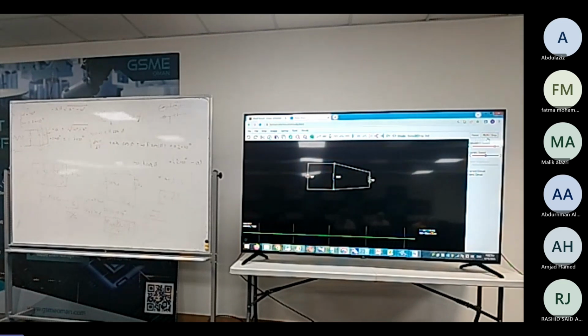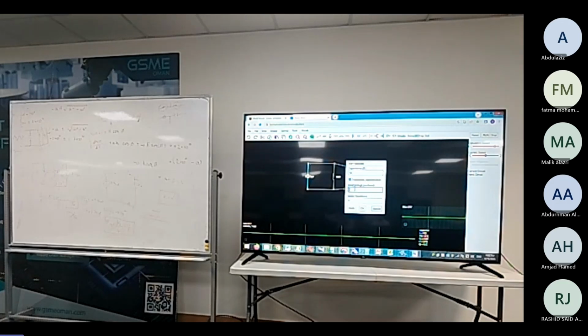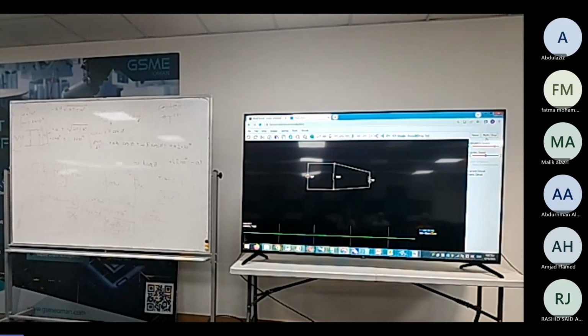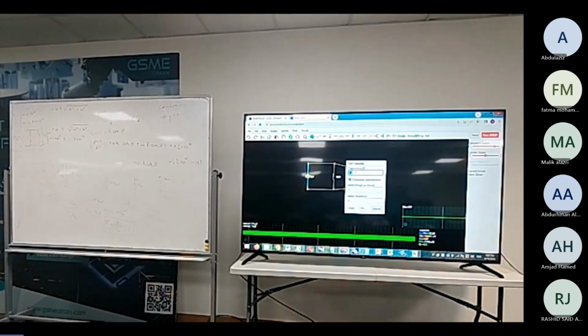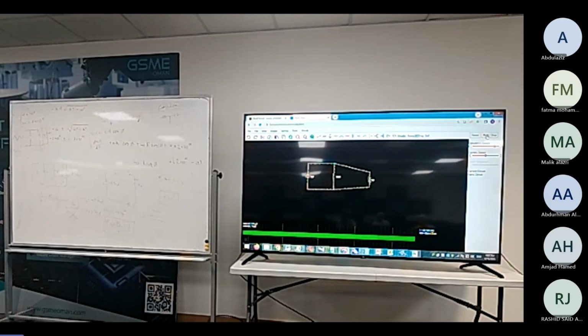One uses transient simulation, solving the differential equation. And the other way of solving is based on assuming that every signal is the result of different harmonics. So it tries to solve for all the harmonics and put them together to generate a signal. That's called harmonic balance. And in the simulators that use harmonic balance, there are features for simulating the envelope. That's what we call envelope transient. Later, when we start working on the simulators in RF, we will actually see those different names.